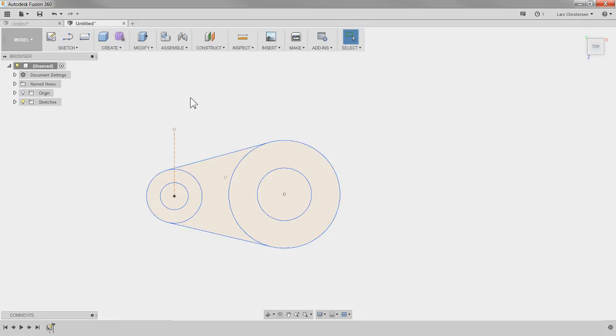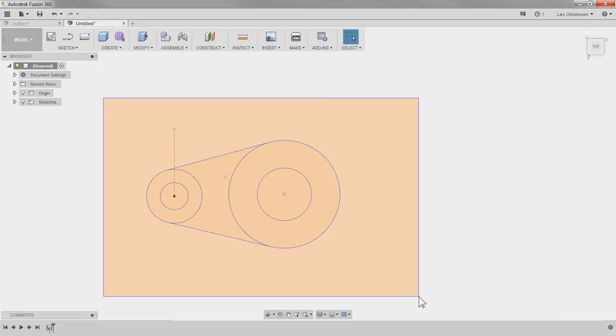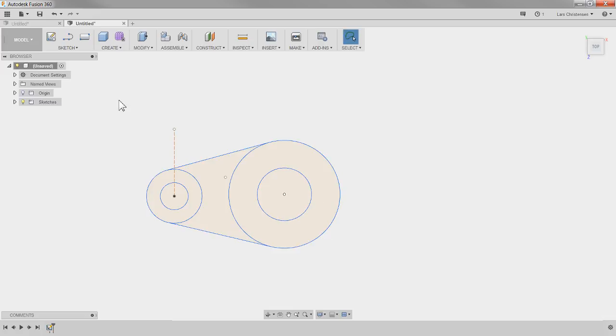Another one that I actually like also to highlight is if you go up to your number keys. If you do number 2, you will actually see that your selection tool changed shape. Now, you probably can figure out number 1 is the default, which is window selection. That's number 1. Number 2 is what is called freeform selection. And by the way, I got to say this. When we talk about number 1, the standard window select that is normally highlighted, you see how it's changing color depending on which way I drag the triangle. You need to know about this.